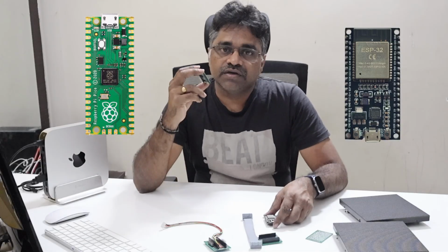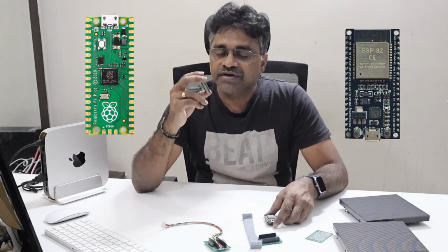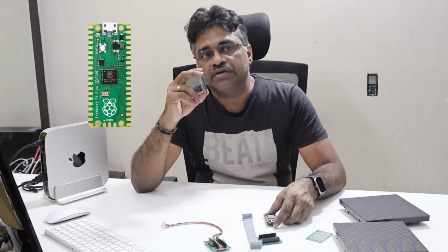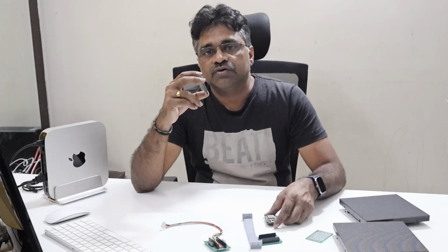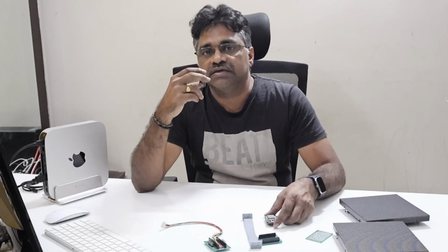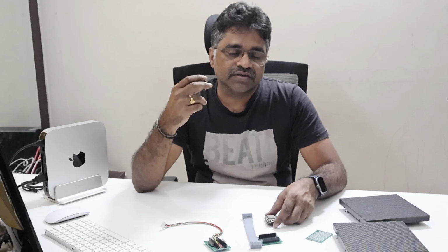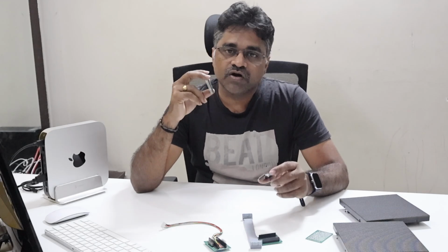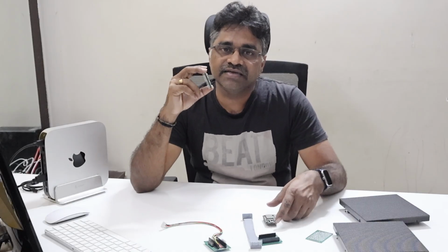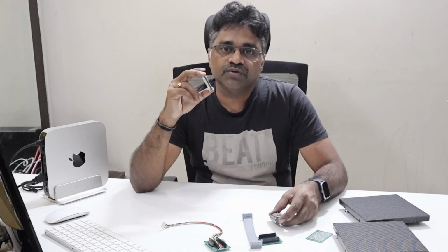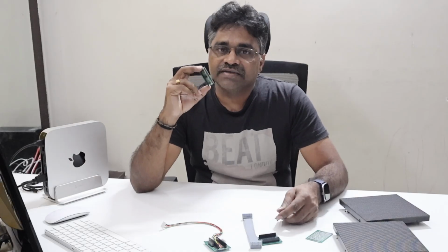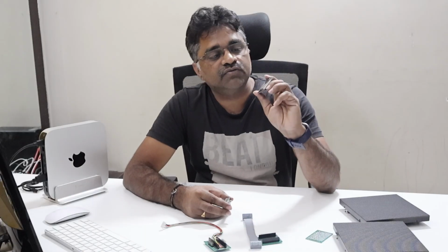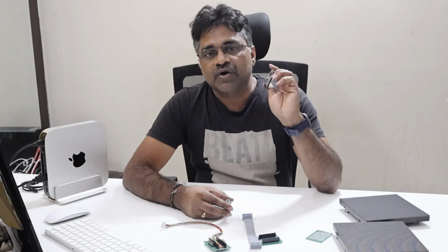One is running the business logic, where it has to prepare the content we want to display. For example, if we want to display some text, we use fonts, and the fonts have to be converted into pixel data to render the text on the screen. If we want to display an image, it has to read the image data and convert it into a pixel map. And at the same time, if we want to switch the program dynamically, the ESP32 has Wi-Fi, so we can use the Wi-Fi to control the program.